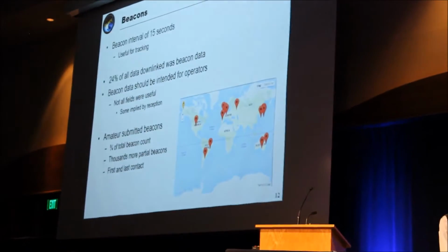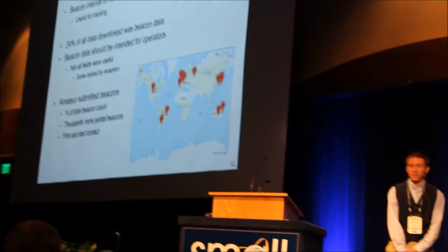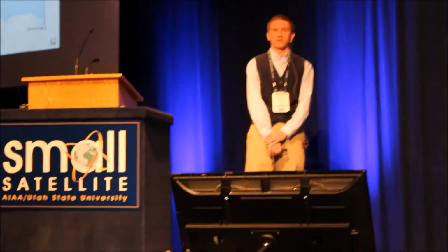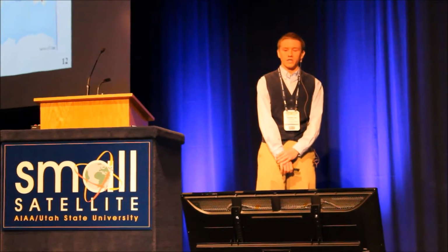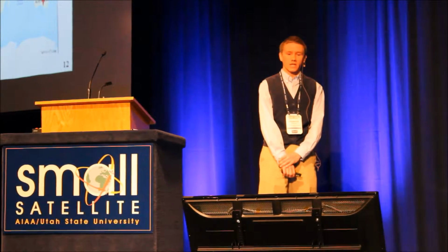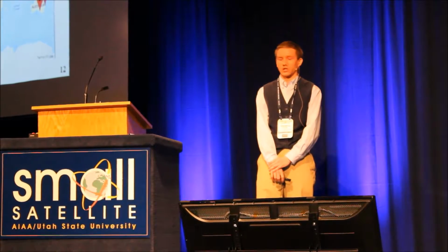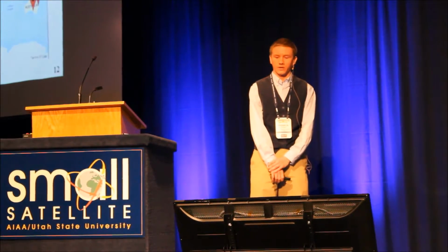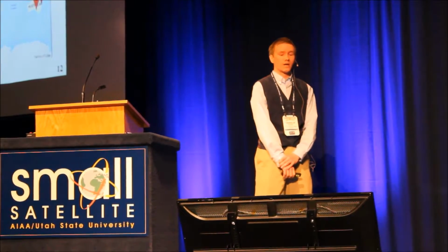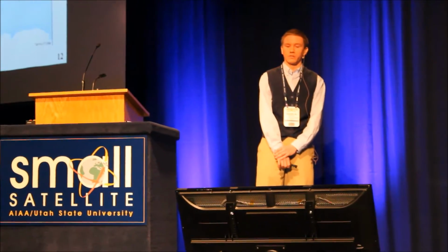Another of the big tools was the beacon. DANDE had a beacon interval of 15 seconds, which without a GPS is really the only way to verify where the satellite was. When you're dealing with that string of pearls issue after launch, successful reception of the beacon is really the only way to verify that your ground station is tracking correctly, that you're pointing where the satellite is, and to figure out which of the various canned objects is indeed your satellite.